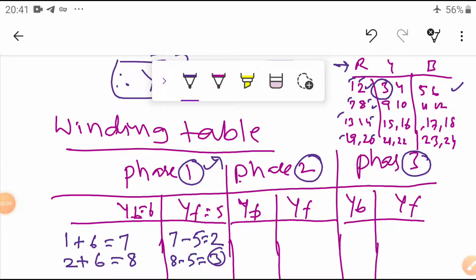Here I am going to go one pole pitch further. That is why, instead of 8 minus 5, dear students, simply 8 plus 5. This is the one twisting point you have to remember. Then 8 plus 5, I get 13. So, the 13 slot, yes, that is mine. Okay, so the 13 slot is over.